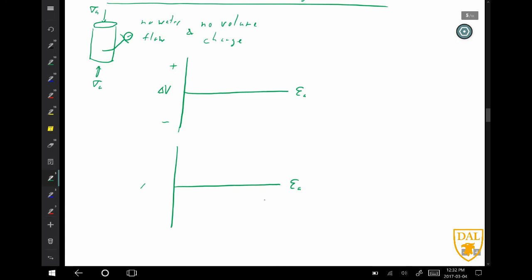And the bottom plot will be change in excess pore pressure. We have increasing pore pressure at the top and decreasing pore pressure or negative excess pore pressure on the bottom. Okay, so there's no volume change as you actually load this thing, right? So, zero.